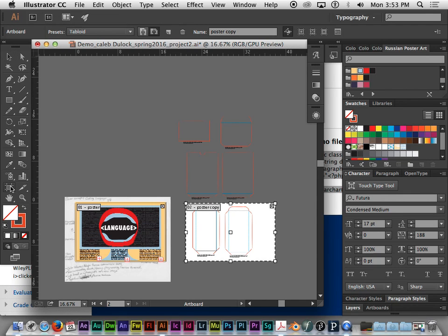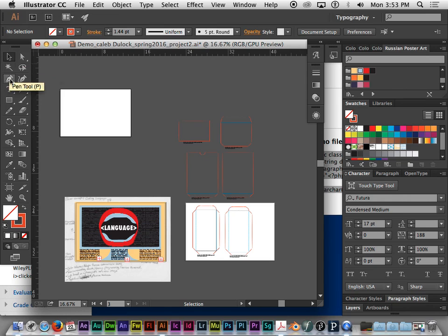And when you turn it on, it activates your artboard that you're currently on screen. And it allows you to click and drag out brand new artboards on screen as well. And again, to get to the artboard tool, you just go down towards the bottom of your toolbar.